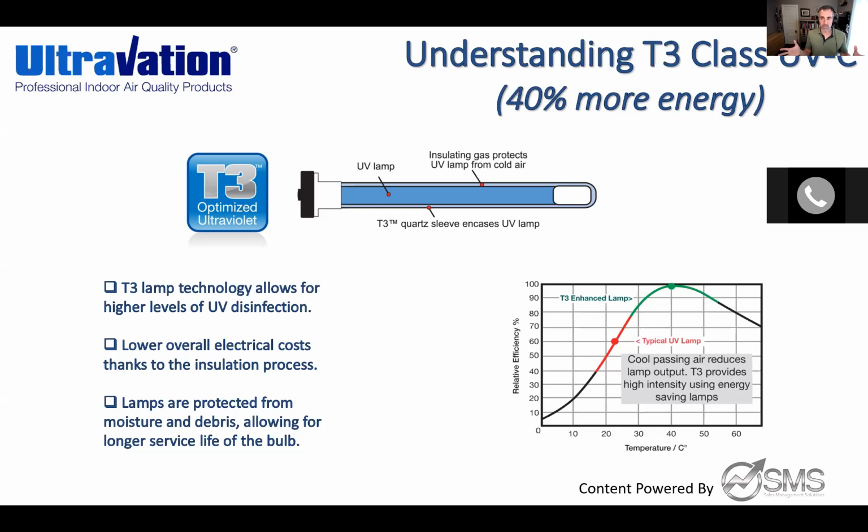All UVC bulbs I have found, no matter the manufacturer, usually come with a 2-year warranty, meaning they guarantee it will stay lit for 2 years. However, if it's a standard UVC bulb, you should be recommended to change it annually, because once you've burned a UVC wavelength bulb 24/7, 365 days that year, you've already lost about 30% of its intensity by the end of that first year, because there's a life cycle to it.